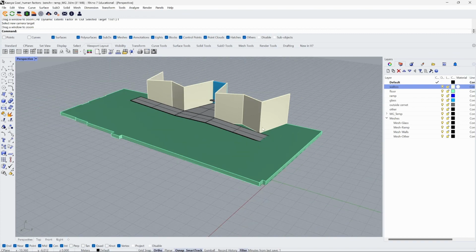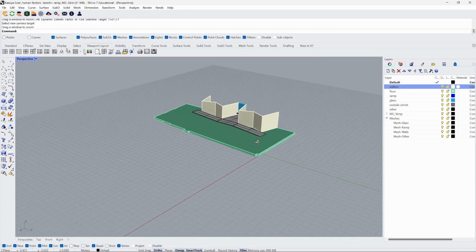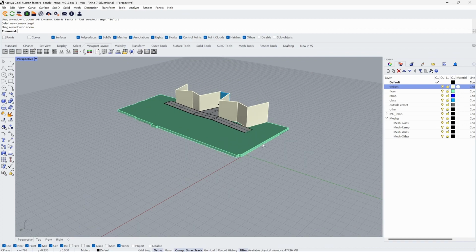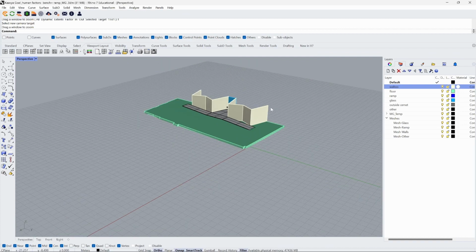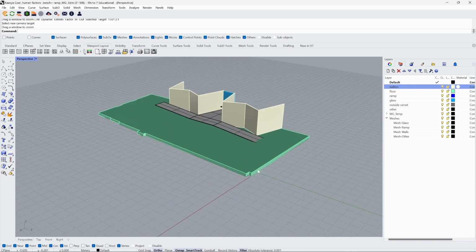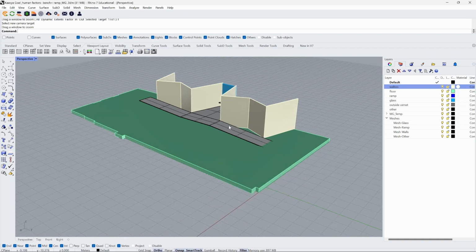It is also a good idea to check whether your model is sitting on the world coordinate plane or flying around somewhere. If it's flying around, it's a good idea to push it down near to the center of this grid plane. Okay, so our goal here is to mesh the Rhino geometries, and what we also need is that these geometries all have materials assigned. These colors Rhino shows us, maybe assigned via layers, will not come across when we export this to Unity.